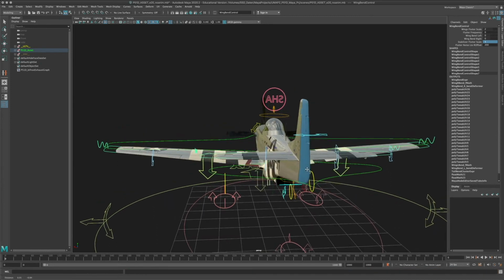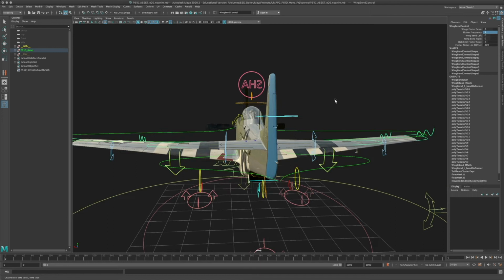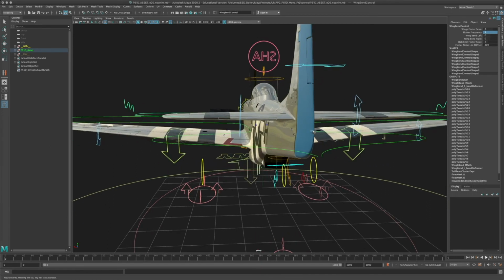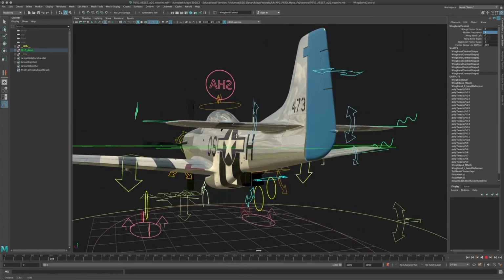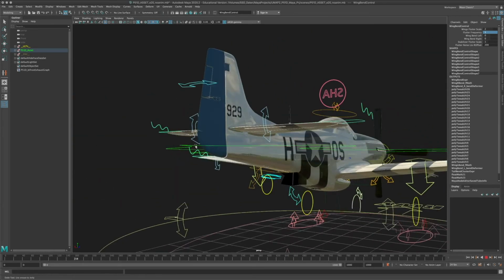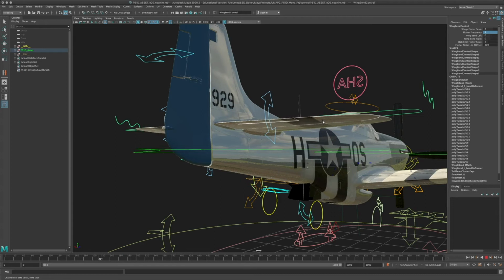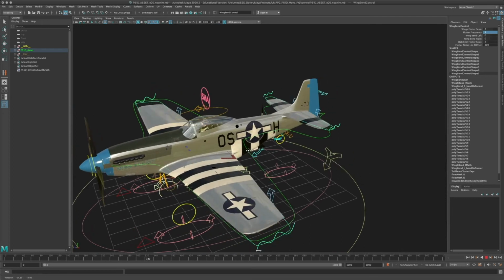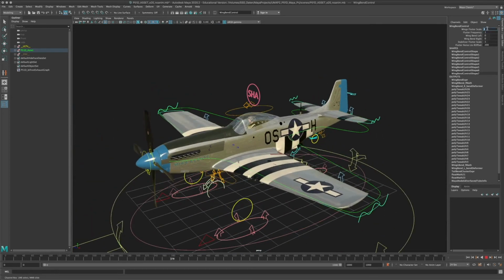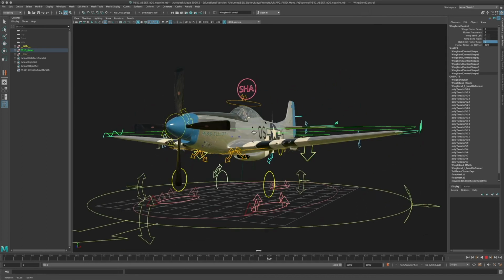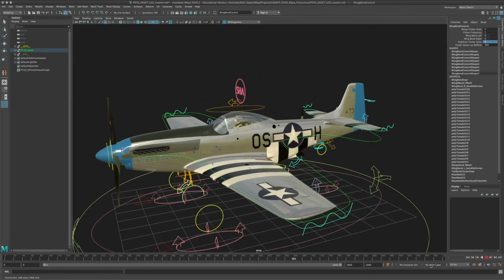If we go back to that flutter frequency, it's actually the same frequency for all of them. You will see that the stabilizers are also fluttering. So when the engine starts, they will get a pretty big push and flutter. But in flight, you would usually never see that. As soon as the plane has left the ground, you would pull up, probably just animate those wings flutter scale and stabilizer flutter scale down to 0 or a very, very low value.